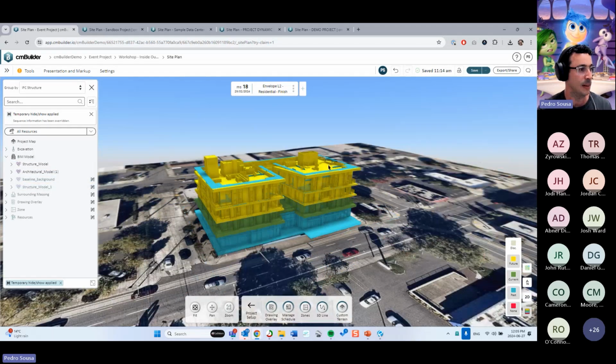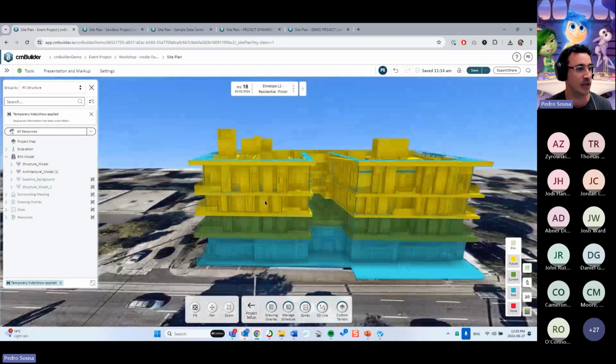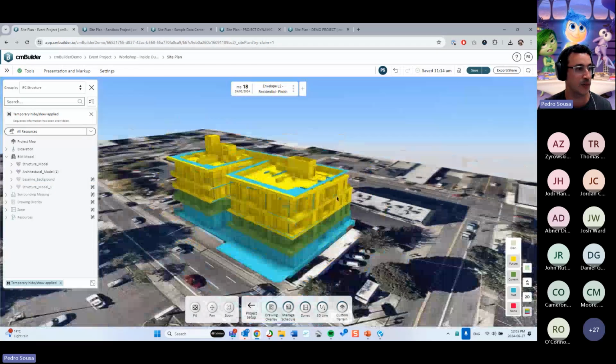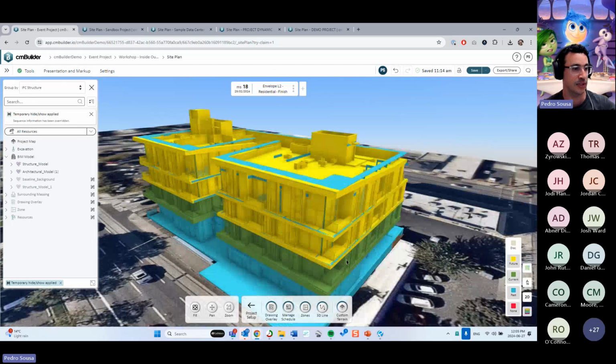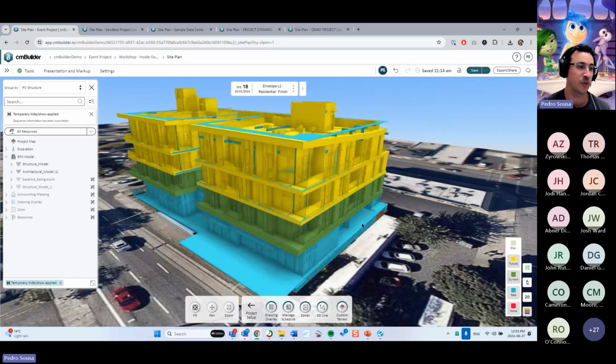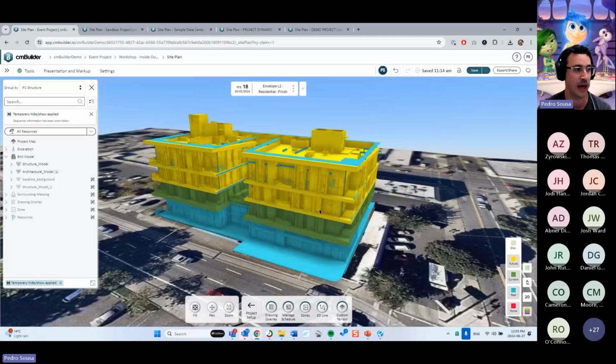So these two, but as you can see over here, I have parts that are colored in very different ways. All the parts that are colored in yellow are parts that are showing in the future milestone compared to this one. The ones in green are the ones in this milestone, and the ones in blue are the ones in the past milestone. You can choose to hide elements on this view based on how they are colored.